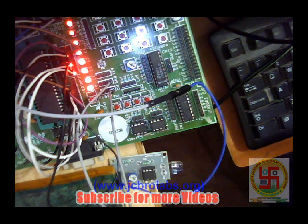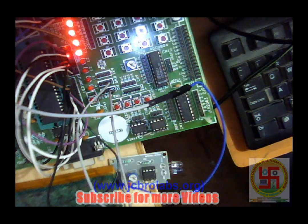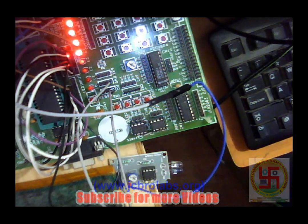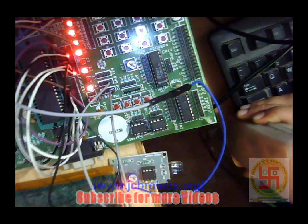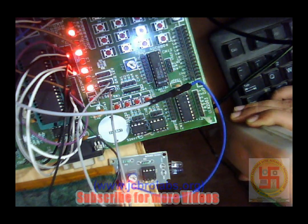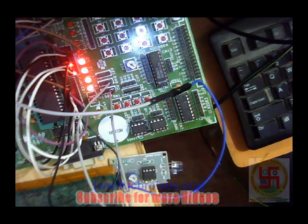Now we have connected the output of this IR sensor to pin 1.0 of the microcontroller. As we have discussed in our programming part, when there is no obstacle in front of this IR sensor, half of the LEDs will turn on and half of the LEDs will remain off, as right now there is a pattern. And as soon as there is an obstacle like this one, the LEDs will start blinking alternatively. So this is how our program is working. When there's an obstacle, the LEDs are blinking alternatively, and when there's no obstacle, half of the LEDs are on and half of the LEDs are off.